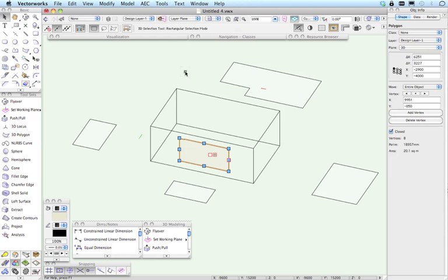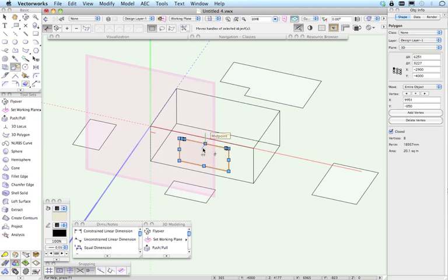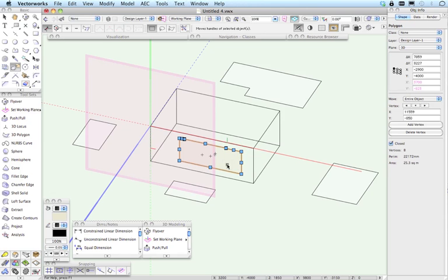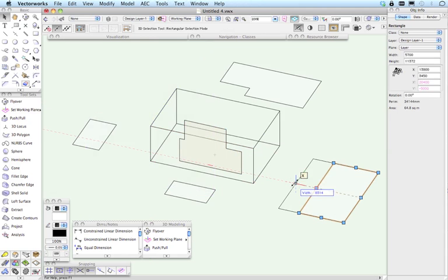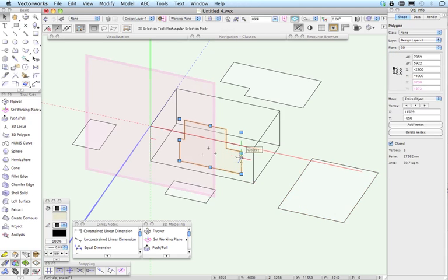It's usually fairly straightforward. You need to be disciplined about where you're drawing objects and what you have this set to, and you need to understand that things to use Add and Clip Surface need to be on the same plane. One other thing I wanted to mention was that if you double click on an object, as well as setting that as the working plane, that then allows you to modify that object. So that was modifying that polygon. If I double click on this object, then I can modify that, and so on.